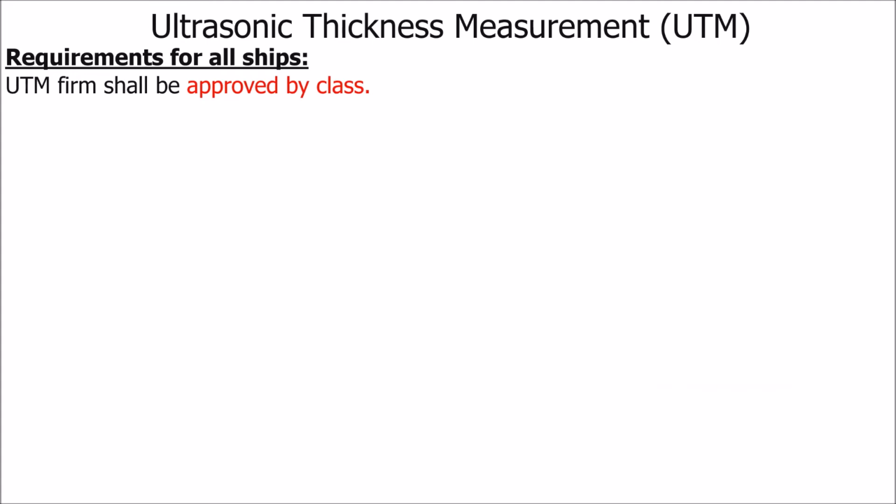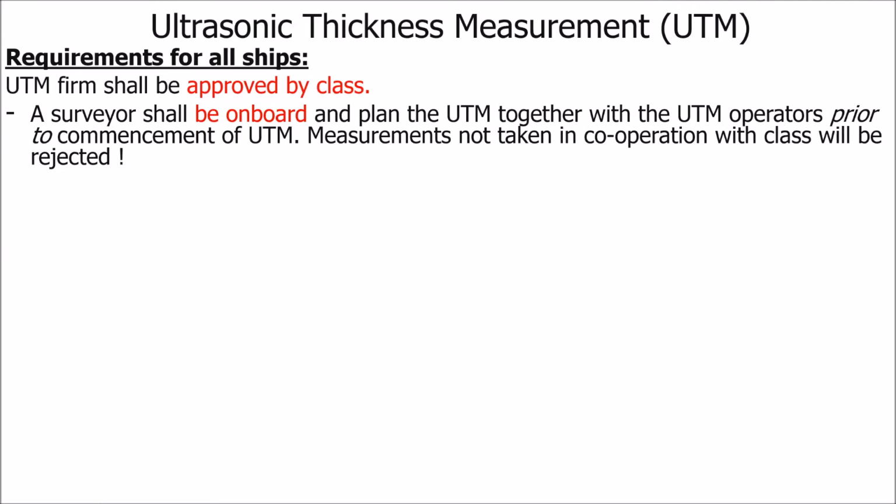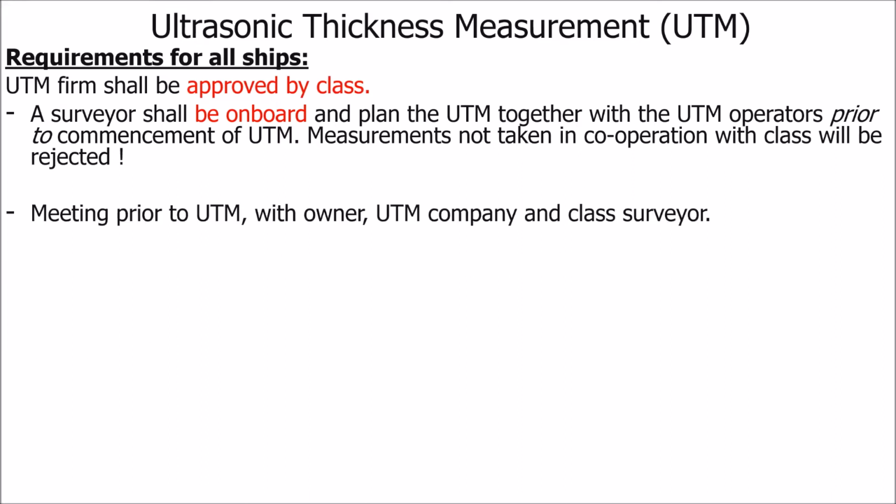So there should be a surveyor on board to plan the ultrasound thickness measurement together with the UTM operators prior to commencement of UTM. Measurements not taken in cooperation with class will be rejected. Well, that may happen. I've seen those UTM firms working without class, so well, I don't know. And there should be a meeting prior to this UTM with the owner, the UTM company, and the class surveyor.